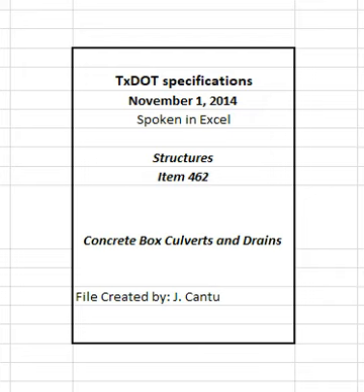Furnish material for machine-made precast boxes in accordance with DMS 7310, reinforced concrete pipe and machine-made precast concrete box culvert fabrication and plant qualification. 2.2 Fabrication. 2.2.1 Cast in place. Meet Item 420, concrete substructures and Item 422, concrete superstructures. 2.2.2 Formed precast. Meet Item 424, precast concrete structural members, fabrication, TxDOT.